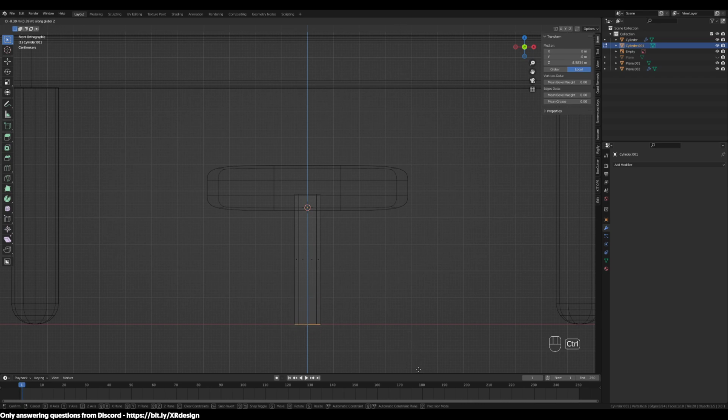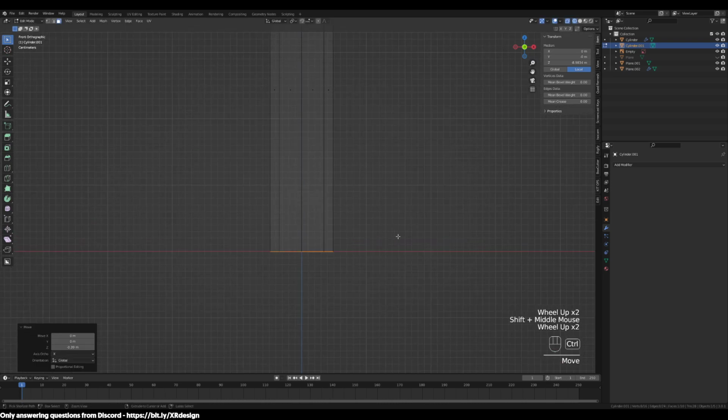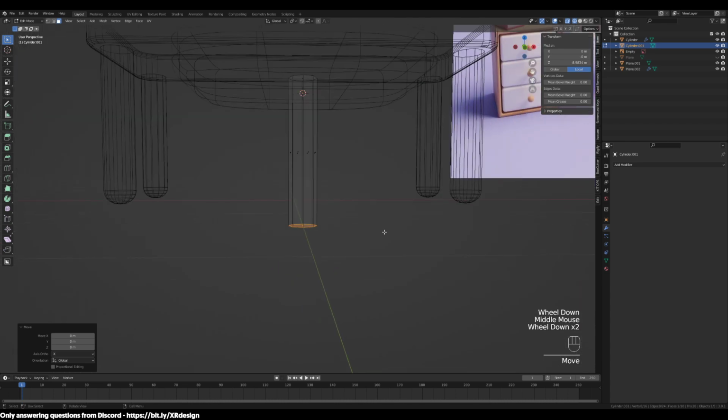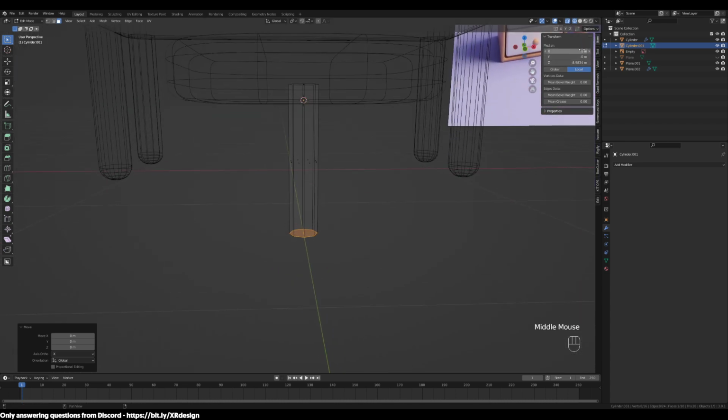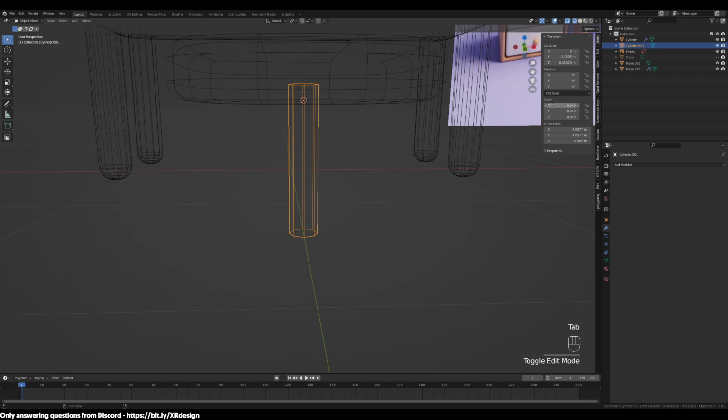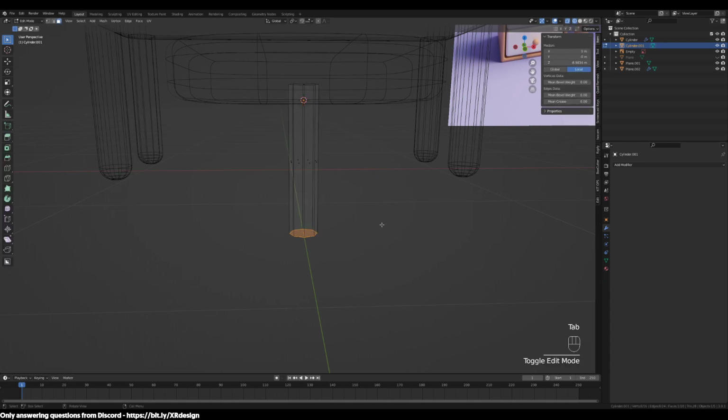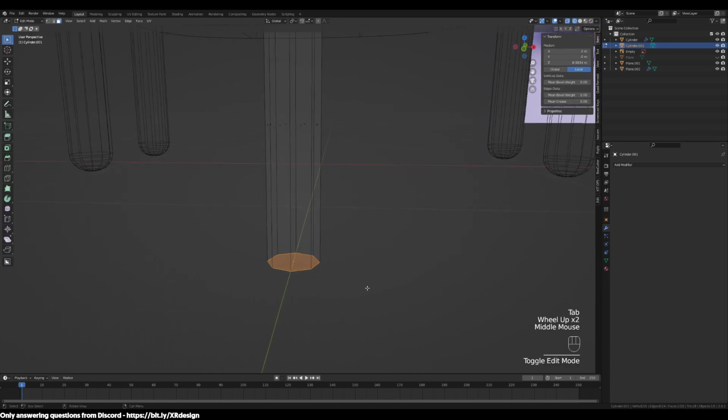And then just using Adam's tip in Discord, if I hit G Control, it'll snap on those little squares. But I want it to snap onto that red line. And let's just check if we have uniform scale value. So we do. We could reset it, but if XYZ is the same, it doesn't really matter. So in edit mode, hit Control B and create that bevel. I'm just decreasing it a little bit because we won't need that much detail.